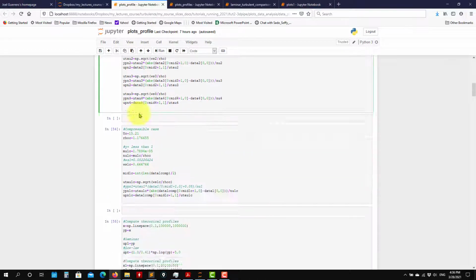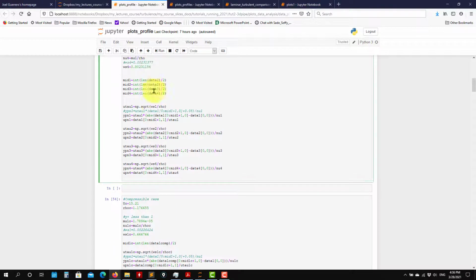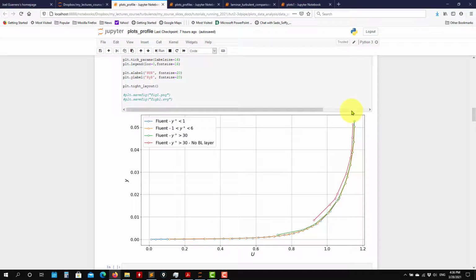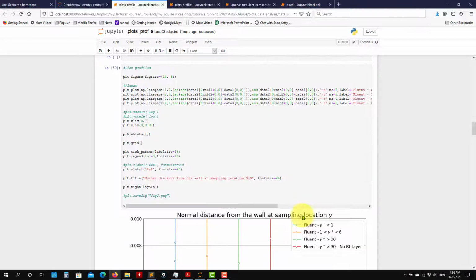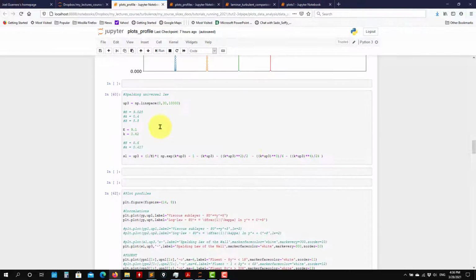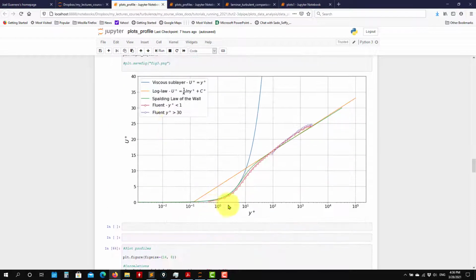You have your flow properties, compute everything. So then you can browse this. So U tau, Y plus, computed in the traditional way, and you just do these plots, okay? So see different meshes. This is the velocity profile. Then here, this is for the mesh. Compute the Spalding law, all that stuff, and you plot here wall resolving and wall function.